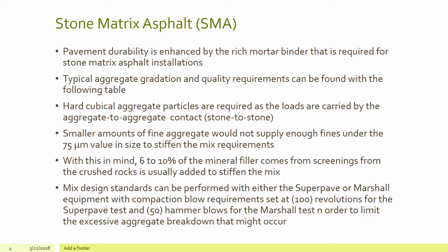Pavement durability is enhanced by the rich mortar binder that is required for the stone matrix asphalt installation. Hard cubical aggregate particles are required as the loads are carried by, again, aggregate-to-aggregate contact, or stone to stone.